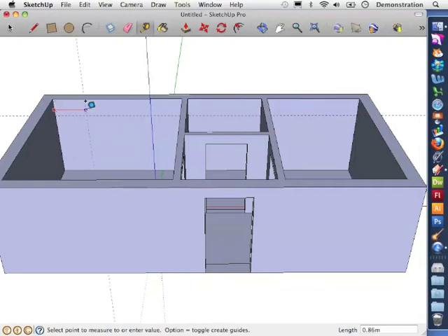So I'm going to click. This time the arrow is red. This is showing me I'm moving out horizontally from the wall there. And there's 0.75, which again I can do with my eye, or I can click and type in the correct dimensions down at the bottom, which is what I'm going to do. So let's put in the length, 0.75, press enter. It moves. I can now get my rectangle tool and click at the intersection of my 2 guidelines.